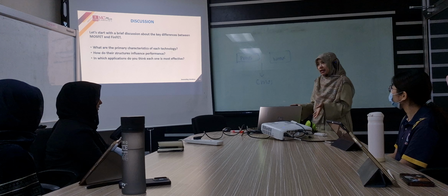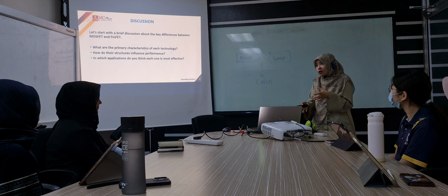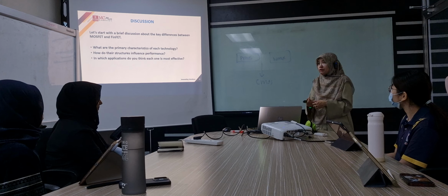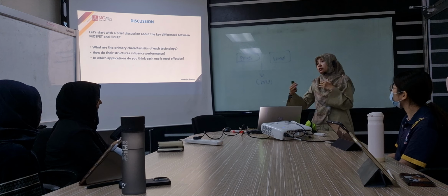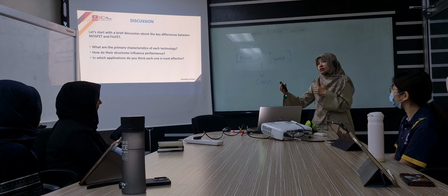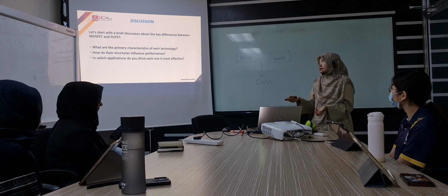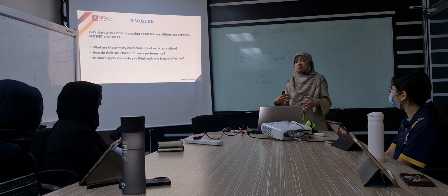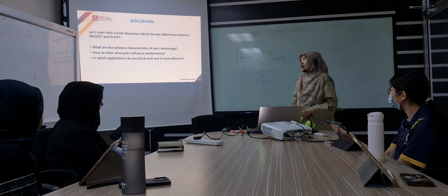More complex, because we want to avoid the power consumption, the timing problem, and the issue with threshold voltage. We want to conduct the MOSFET in terms of three conditions: triode region, linear region, saturation region, and also pinch off saturation and velocity saturation. It will be complex when you have more complexity on chip, so better to switch to FinFET. But the understanding of MOSFET, I could say, is very important.